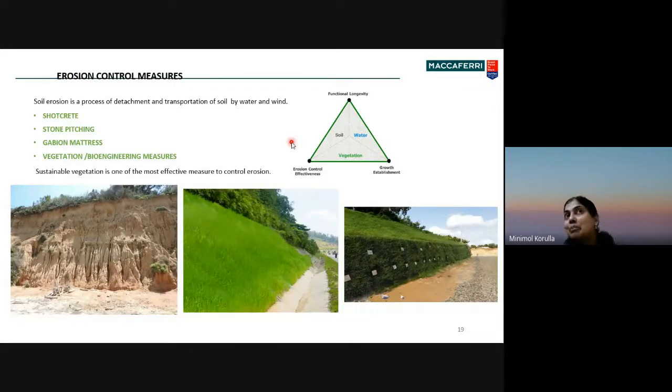In most of these landslide affected stretches, my observation is that whenever it got cut, at that time itself, if we can do erosion control, then many of the disastrous landslides can be avoided. But at that time we will not be ready for spending that 10 rupees, and instead of 10 rupees it will go to thousands or lakhs.